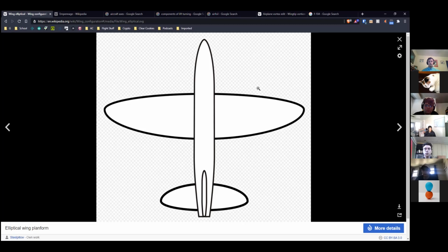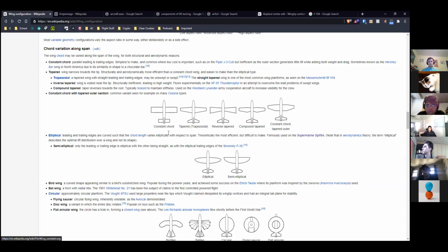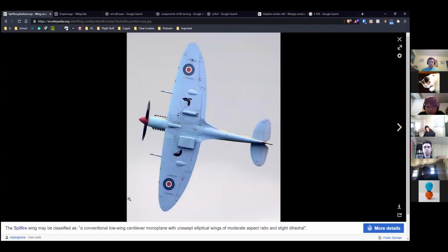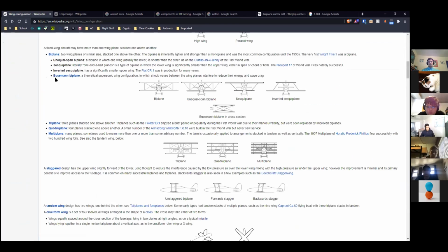The wing planform that creates that lift distribution is not an ellipse itself, although if you use an ellipse as your wing planform, you'll get really close still to an elliptical lift distribution. So sometimes that's used to approximate it. But this is basically the wing shape that the Spitfire had, because they figured it out in the 40s and they were like, oh, we should just use that. It'll be so good. But it turns out it's hard to manufacture. But it means they did have a plane for a while that flew an elliptical planform. So that was cool.